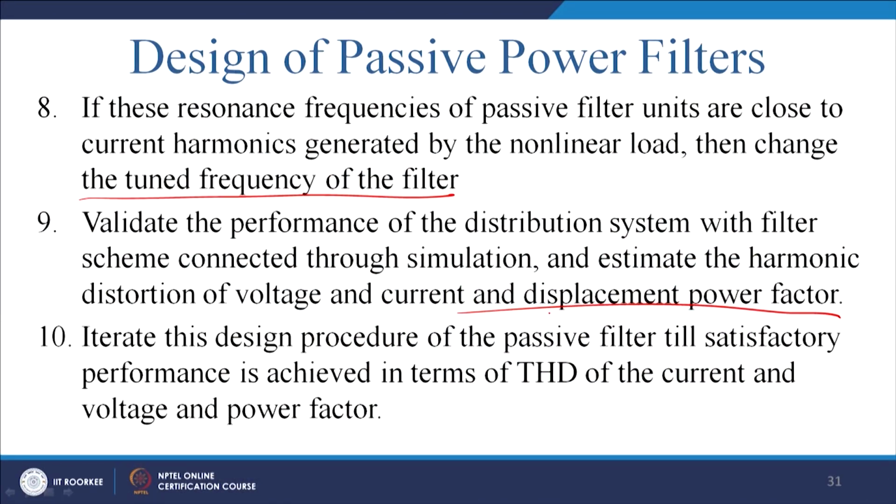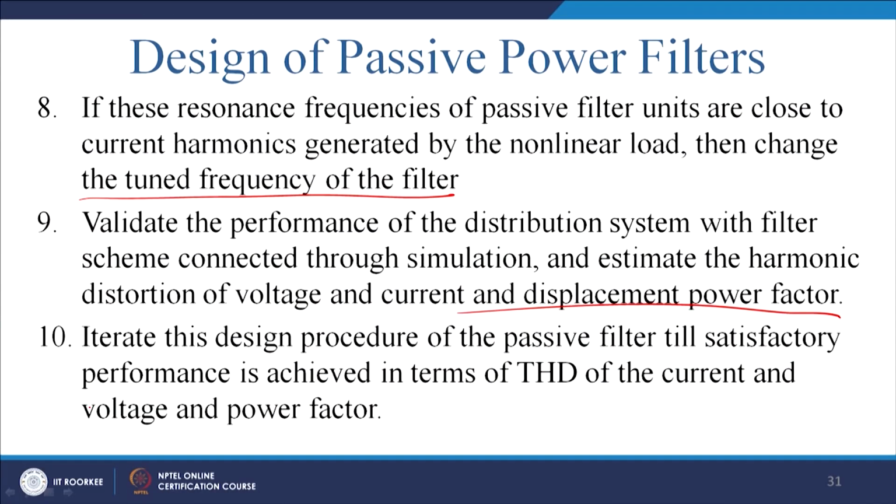Once you want to compensate the high reactive power, then the value of the capacitor required needs to be some value, and unfortunately you may not be able to provide that kind of sharpness, and thus you may not be able to meet the IEEE 519 standard by your proper designing. Then you have to increase the value of the inductor, something like that, and that requires extra cost. So, that is what I am saying, that you have to iterate and converge.